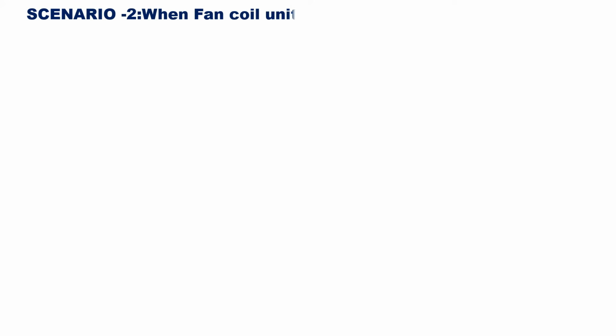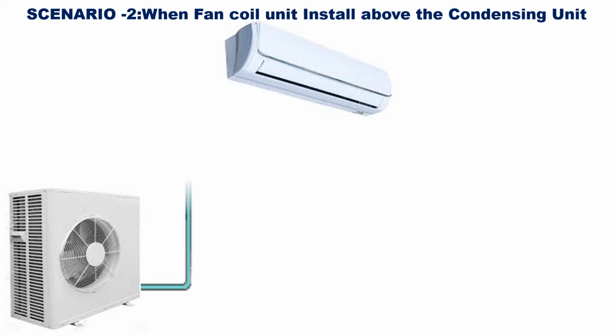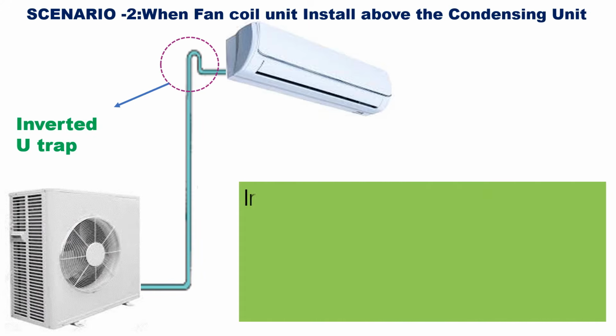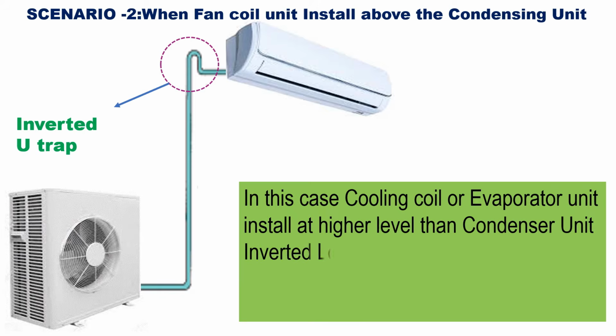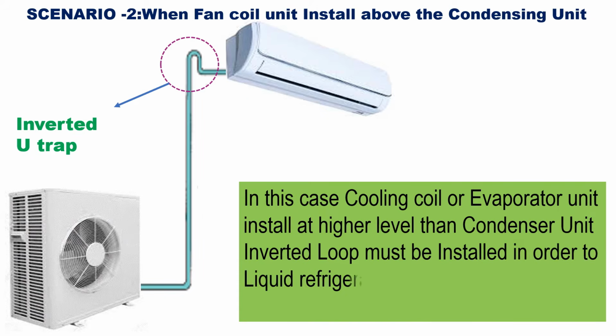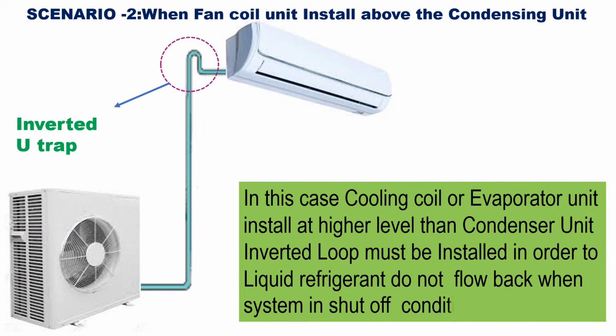How to size the discharge line oil traps. These are installed or formed in high discharge risers to prevent oil from draining back to the compressor head during off cycles. If oil is present in the head, a dynamic pressure will develop as the compressor restarts, resulting in damage to the compressor valves, blown gaskets, and possibly broken connecting rods and drive shafts.